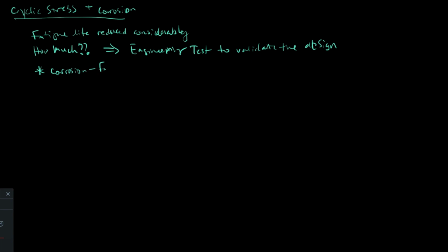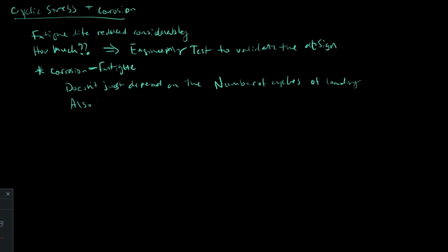One of the things that is important to note is that corrosion fatigue, as this is called when you have cyclical stress and corrosion, doesn't just depend on the number of cycles of loading. It also heavily depends on time.